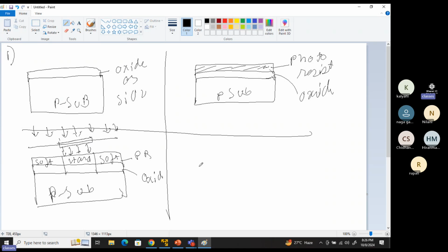Now after this step, you will be adding one more step here, in which this part will be planarized properly before etching is done. Before etching, they will first planarize this area, because it's hard now. It will be planarized with a planarizing machine. But because this area is very precise and planarizing a very small area is difficult, the cost increases. It will planarize this hard area.